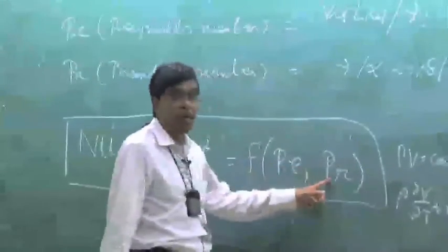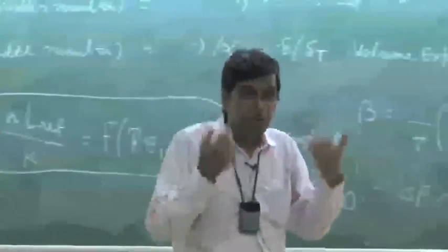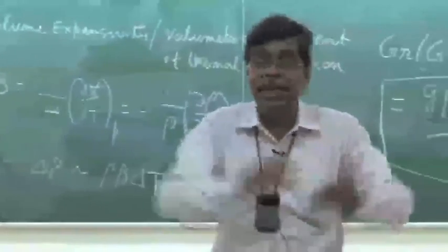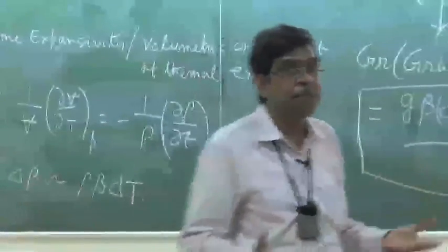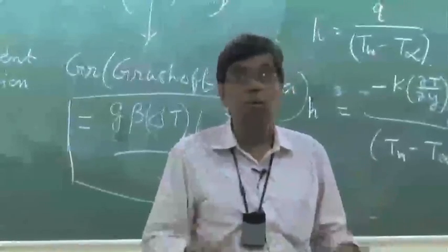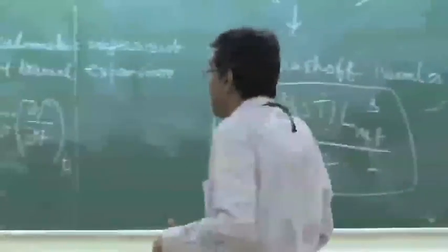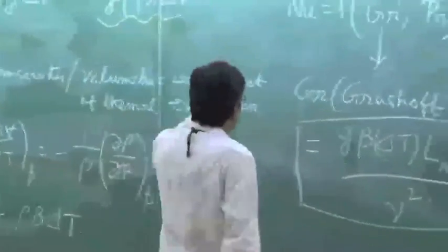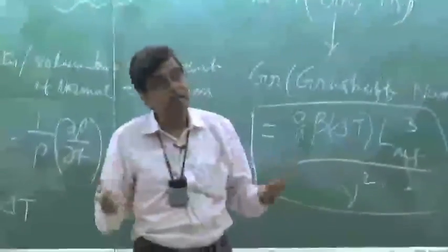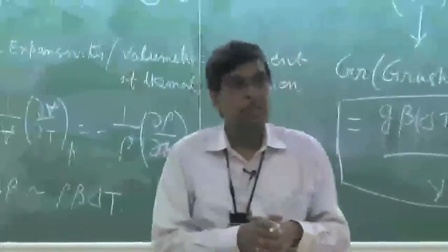with Reynolds and Prandtl, we have to solve for temperature field and the velocity field. And for the solution of temperature field, we have to know the velocity, because the energy equation which involves temperature as the unknown dependent variable contains the velocity as the known parameters, which will be fed from the solution of Navier-Stokes equation. And similarly, to know the Nusselt number, this relationship for free convection flow, we have to solve similarly the temperature and velocity field, where the flow is because of the buoyancy.